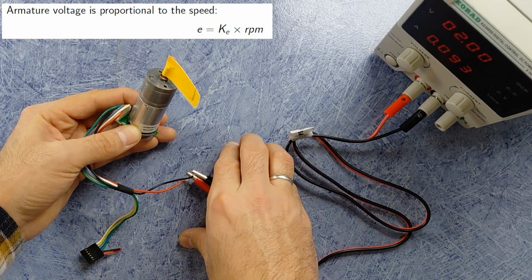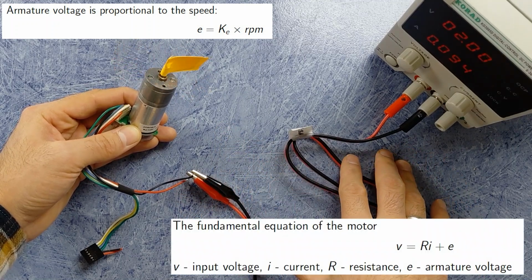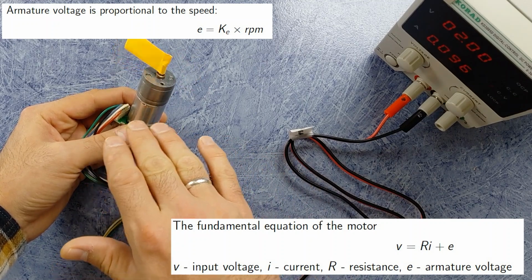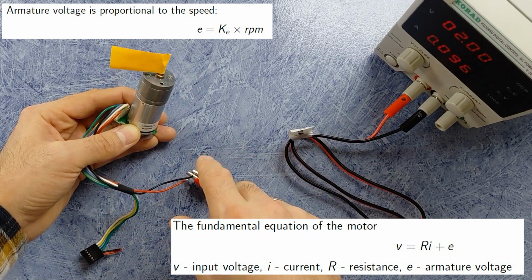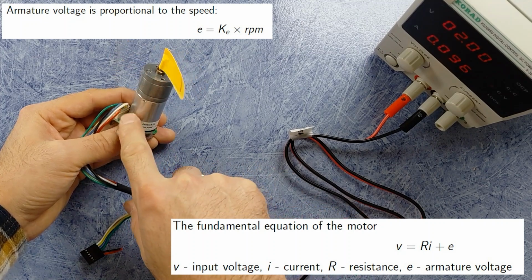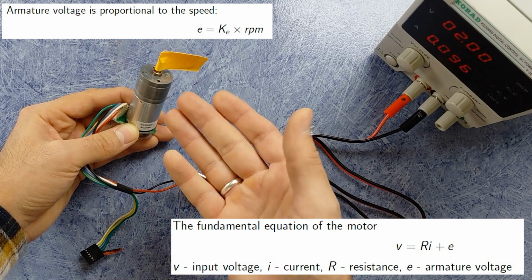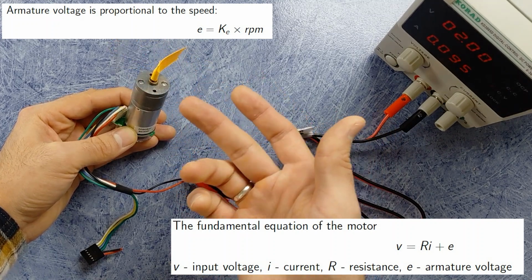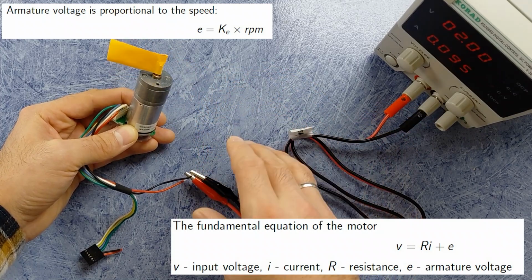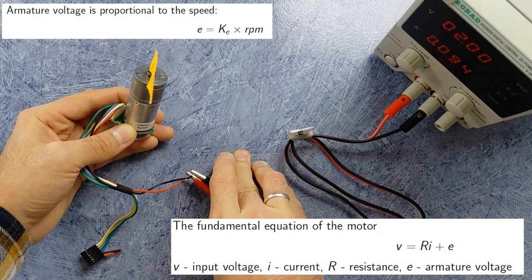From that we can write another equation: the voltage we provide is equal to the armature voltage that I just demonstrated plus the current multiplied by R. So the resistance of the DC motor creates some voltage drop. When we don't have any load, when it's just spinning without any load, I is really low, so we can assume that the input voltage is equal to the armature voltage.